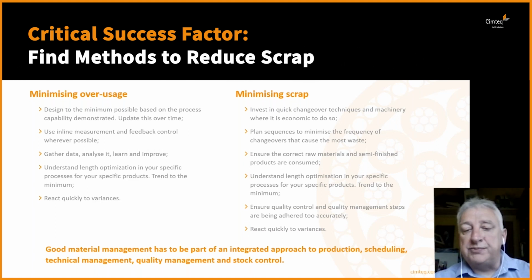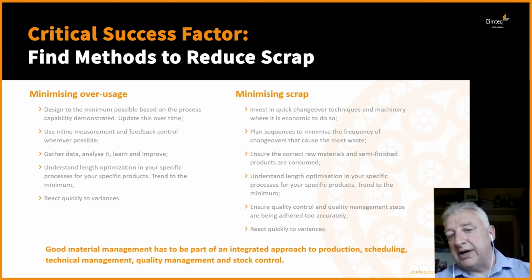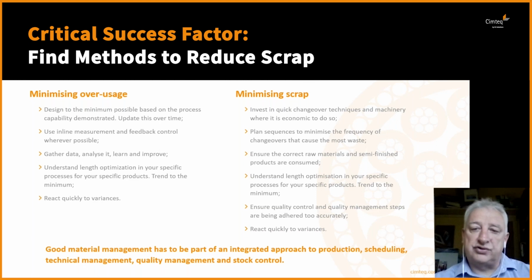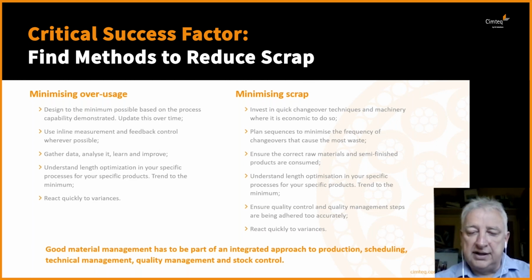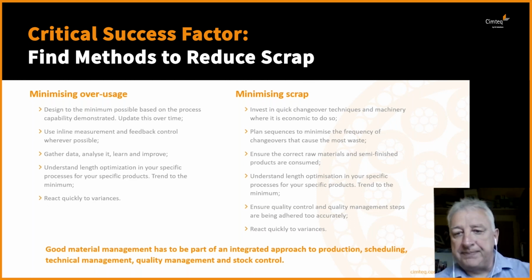Planning does play a huge role in reducing scrap in terms of the sequencing of cables through the day to minimize changeovers, particularly on extrusion, as you know, around color changes, polymer changes, and elastomer changes. Those are where most scrap gets generated, and planning and scheduling has a huge role to play there in streamlining those losses.